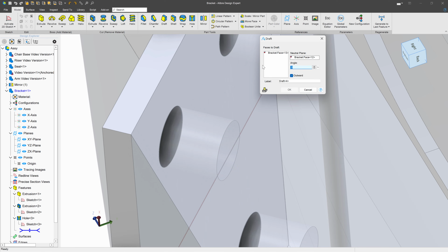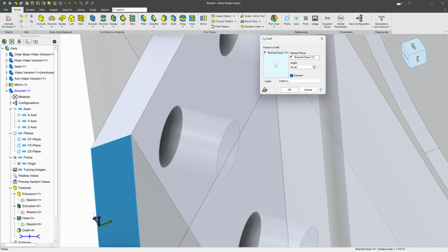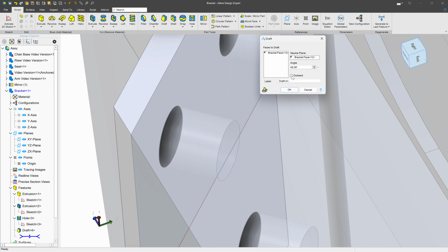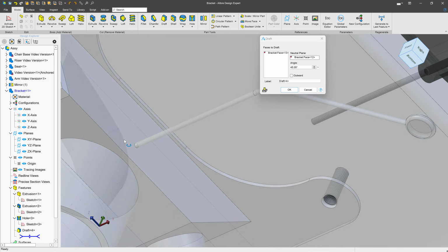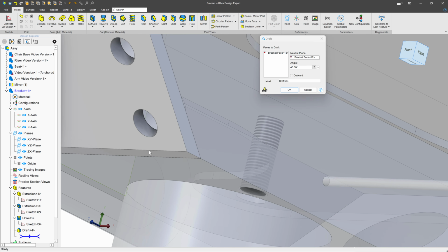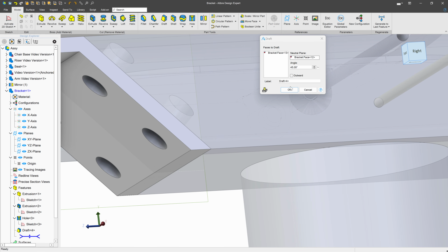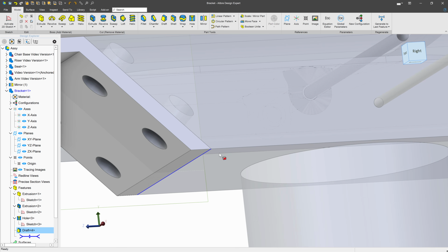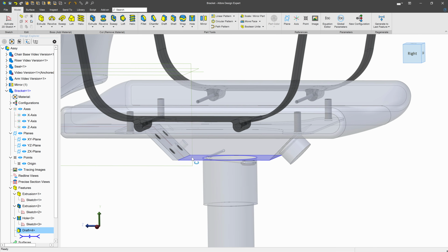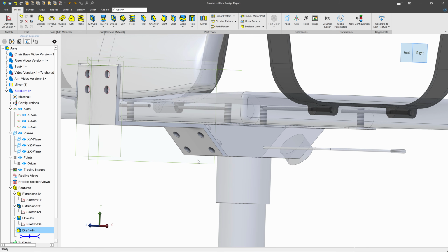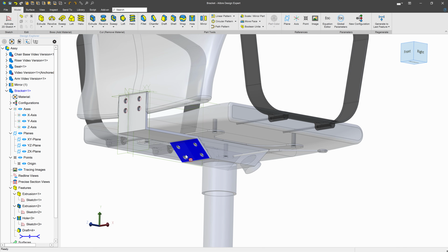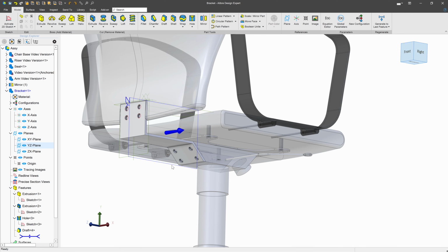Next, I'll go to my angle. I'll go with 45 degrees and we'll see how that goes. And I'll change that draft inward. And now our bracket ends flush. So you can always do something like an extruded cut or whatnot, but I think a draft really has a simple elegance about changing the position of faces like that. And that is our intermediate bracket that will update if we update our assembly, and that is made in context. And that is in context editing.